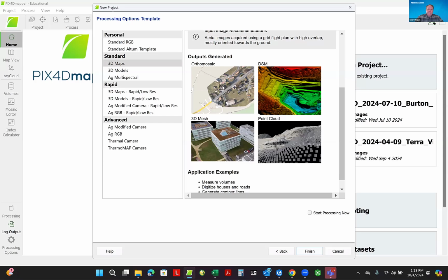So each position in it should be pulled up to pretty close to its correct horizontal or latitudinal position. And so it's ideal for mapping. And that's part of the stitching process, taking away panoramic distortion and pulling it into its correct geopositioning for almost every pixel. Besides that, I mentioned digital surface model.